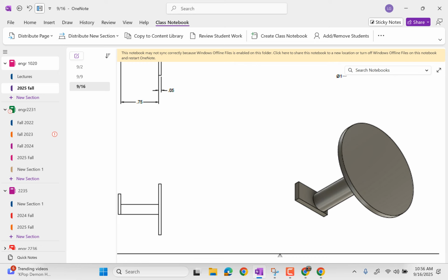The way I'm going to do it, just because we're talking about revolve, is I am going to make a picture like the projection of the shaft part and the disc part, and then I'm just going to revolve that whole thing as one. And then we only have to do one additional extrude at the end. Okay.